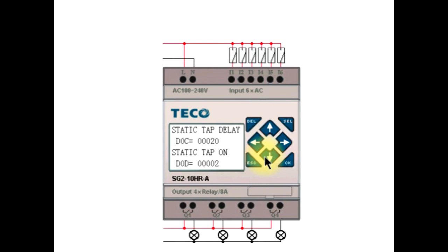So after thinking about that, I thought we could use our blend application to fluidize the material in the sight glass every cycle for just a short period of time to make sure that there is no bridging or static material preventing the sensor from working properly. So what is set here is every 20 seconds, for 0.2 of a second, you get a little puff of air. So if you're running a 20-second cycle, every cycle it would make sure that the sight glass was in the proper operating condition. And this can be very beneficial if you have jobs with a high degree of static or regrind that tends to bridge.